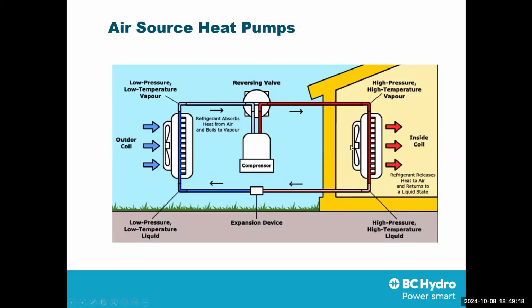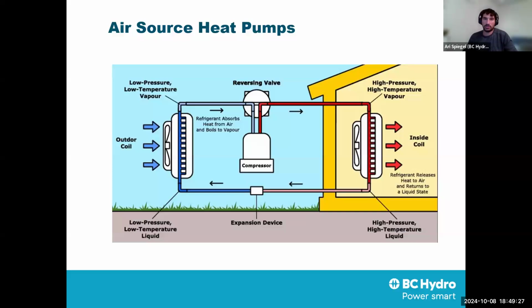So when we talk about a heat pump, what are we talking about? In the residential space, we're often looking at what's called an air source heat pump. A heat pump in general is a device that's used to move thermal energy from lower temperature to higher temperature and make it useful. Similar to how a refrigerator works, the only difference is that a heat pump is a fully reversible system. In this image, it shows the key components of a heat pump.